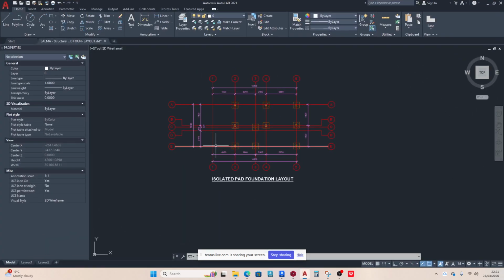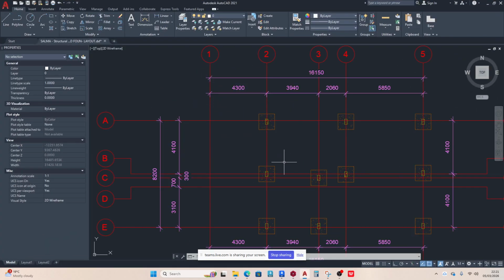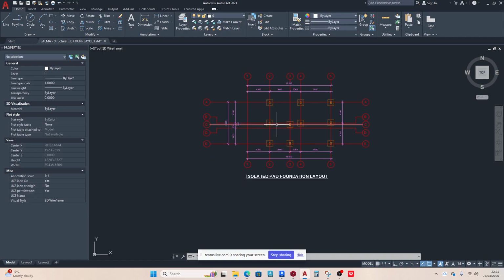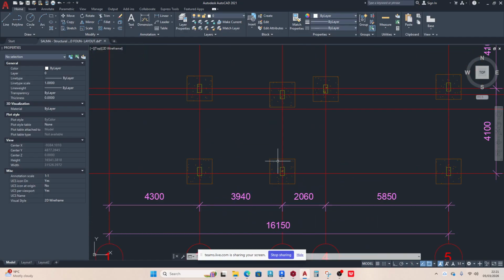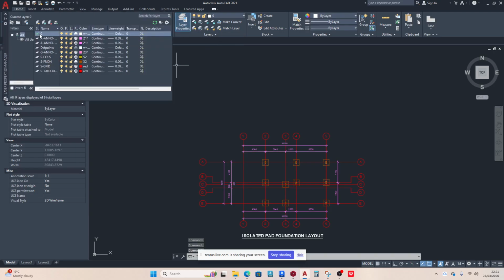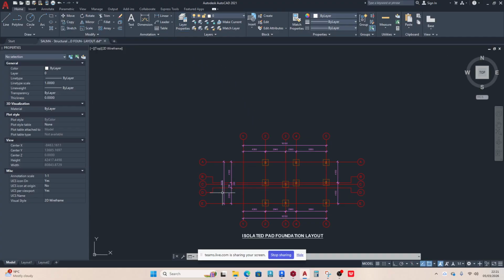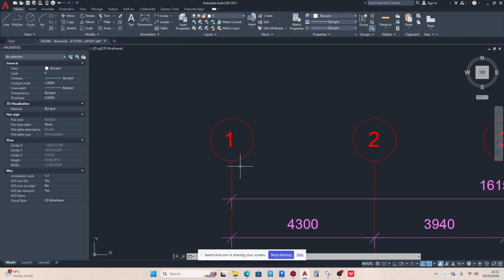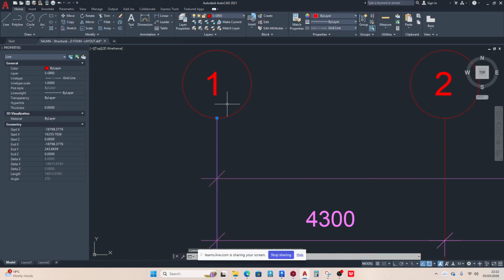So here's my AutoCAD, and this is the exported file. We can see, for example, the layers there. It's only got about 1, 2, 3, 4, 5, 6, 7, 8, 9 layers, right? And if I needed to know which layer each one of them is on, I'll just select, and it shows me here. This is S-Grid, meaning structure grid.